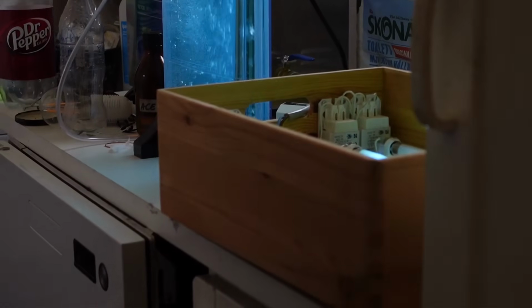With the solution prepared, it's time to preheat the UV exposure box. It takes a couple minutes for the UV tubes to get up to power, and it can mess up your exposure times if they aren't up to temperature.